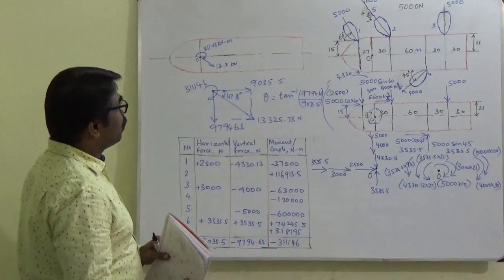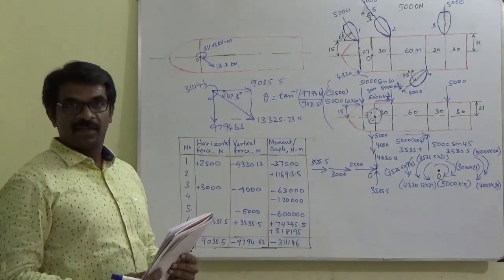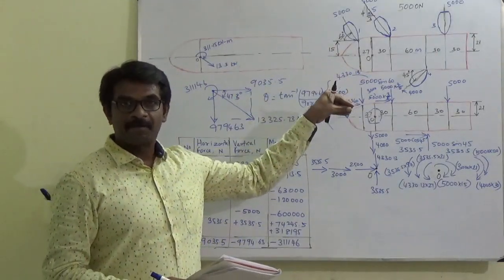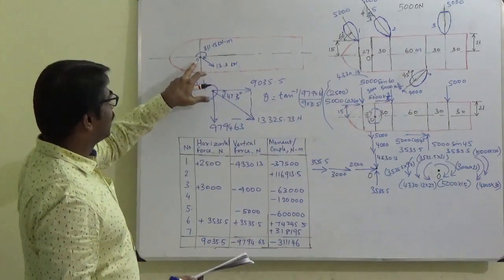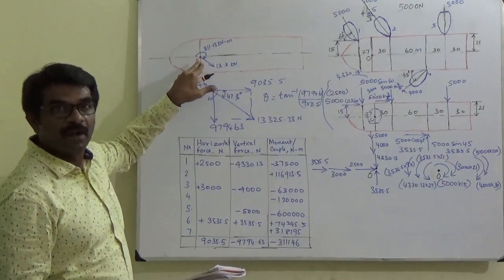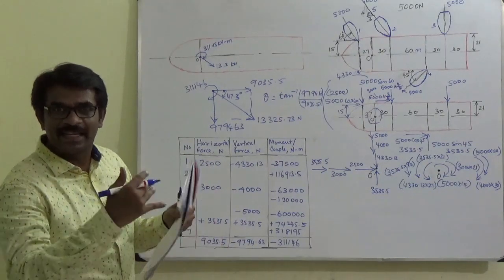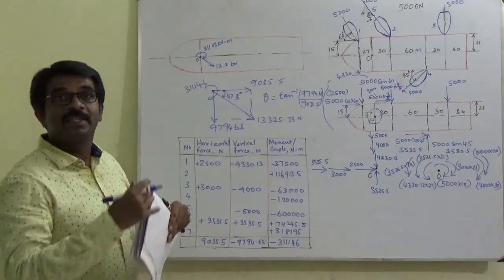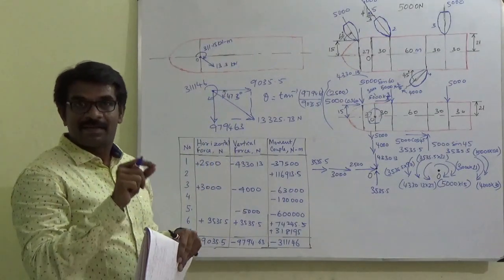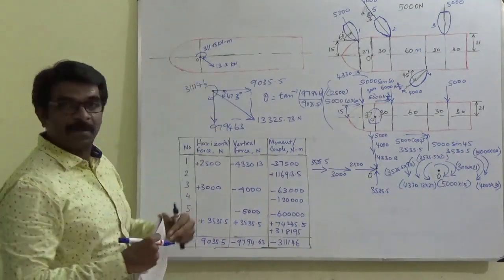Now we have already learned, if you could see the previous slide, we discussed how all these forces could be written. So we can write like this. Now if at all to release this couple, we have to move this force, the line of action of the force. The inclination will not change, but it will move away, either right side or left side based on the direction of the couple. So then we can release this couple.